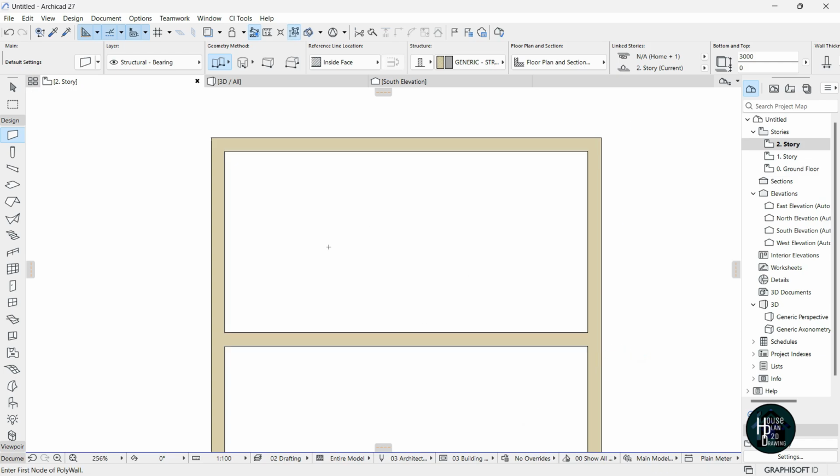Okay, once you do that, put the cursor here, allow it to load up, and let's give a distance of 1675. Click enter. Okay, and I wanted to make sure that the wall is shown at the other side, so click this, and now this stretch I wanted to give a distance of 2000. Click enter and just double click the side. Okay, once you do that,